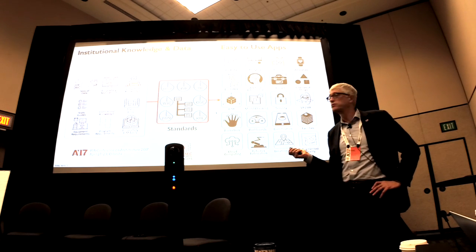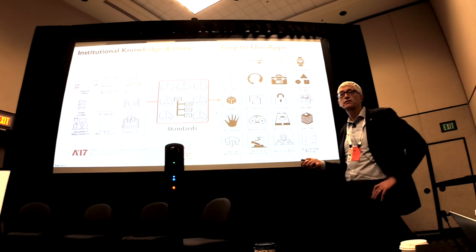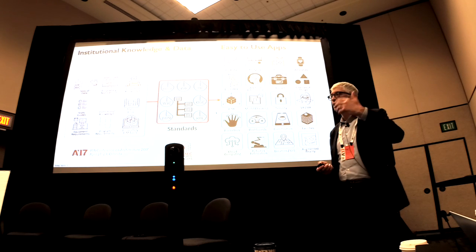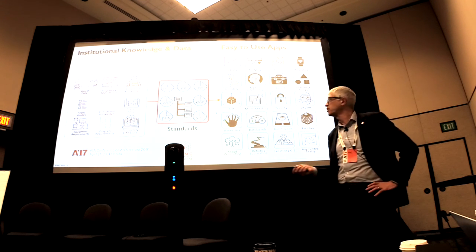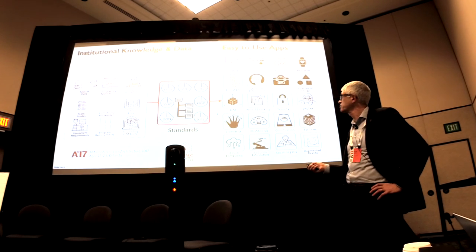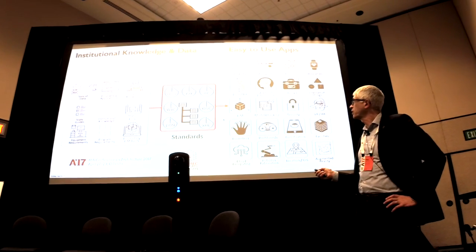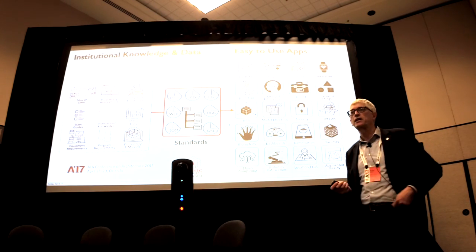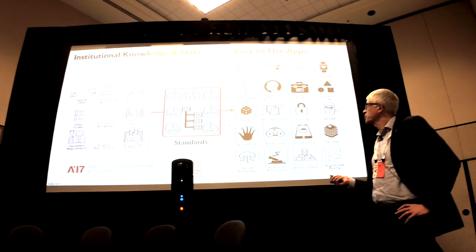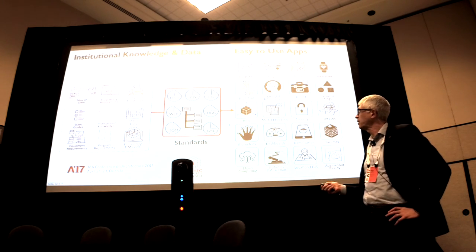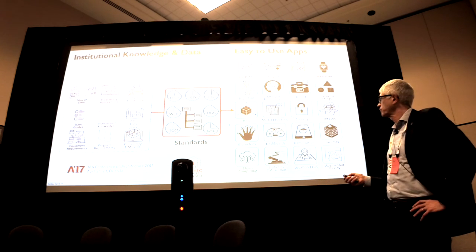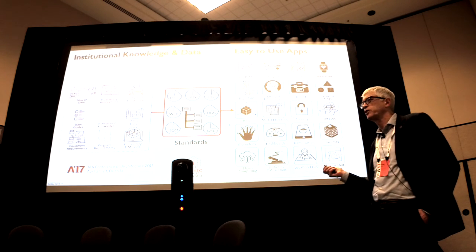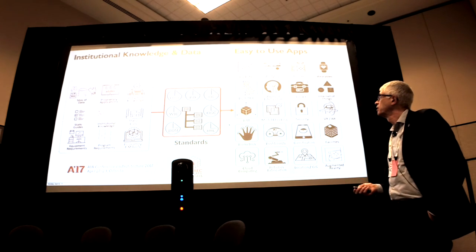Now, there's different kinds of standards. There's standards for how we exchange data. Dennis showed some, how do we go to an API and get data that's posted using XML or JSON. Those are kinds of data formatting standards. But there's also standards that organize information together, like COBie and IFC, that give a structure, a schema to data, that take some time to put together and make these things work. So what I want to talk a little bit about is how that process happens, and then what you can do with it. An example, a couple examples.